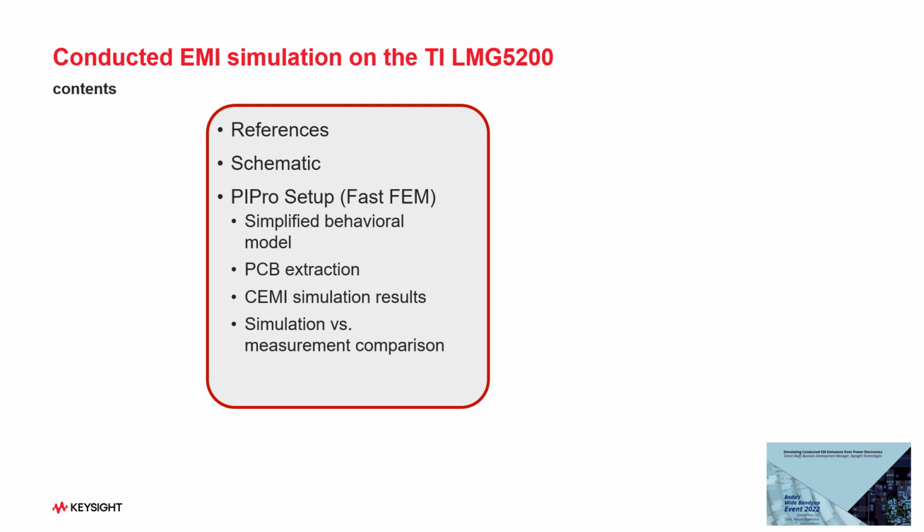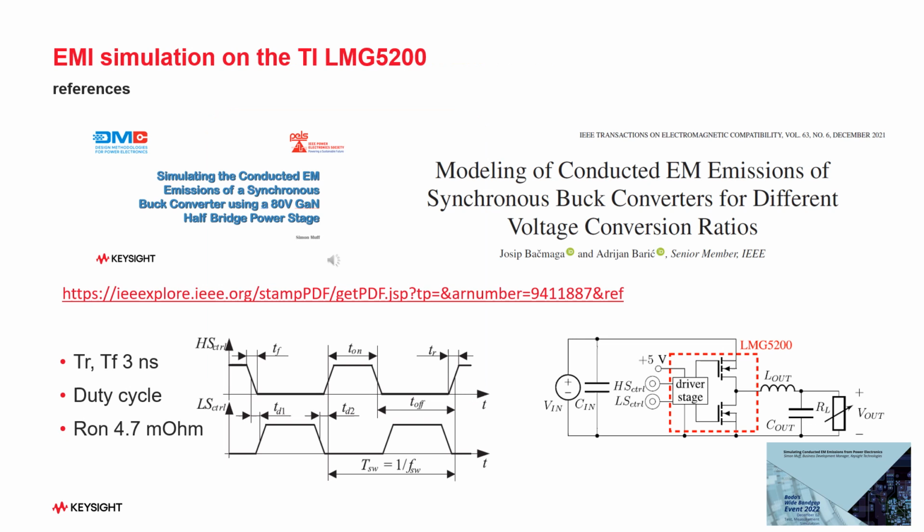I show you the schematic, how to set up the simulations in Power Integrity Pro with our fast FEM technology, to use a simplified behavioral model and run the PCB extraction to get fast to the conducted EMI simulation results. And of course, we compare them to measurements.